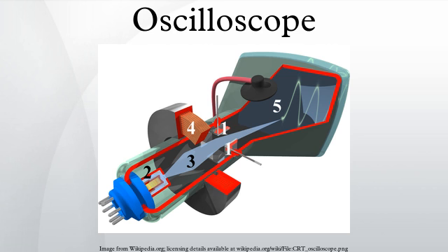Partway through the amplifier is a feed to the sweep trigger circuits, for internal triggering from the signal. This feed would be from an individual channel's amplifier in a dual or multi-trace oscilloscope, the channel depending upon the setting of the trigger source selector. This feed precedes the delay, which allows the sweep circuit to unblank the CRT and start the forward sweep, so the CRT can show the triggering event. High-quality analog delays add a modest cost to an oscilloscope, and are omitted in oscilloscopes that are cost-sensitive.